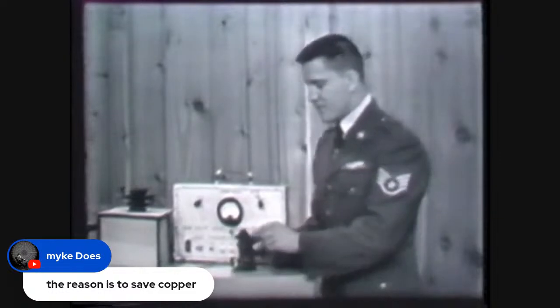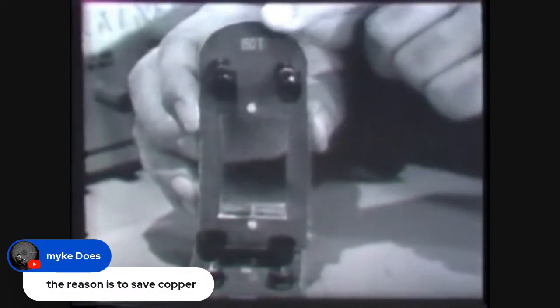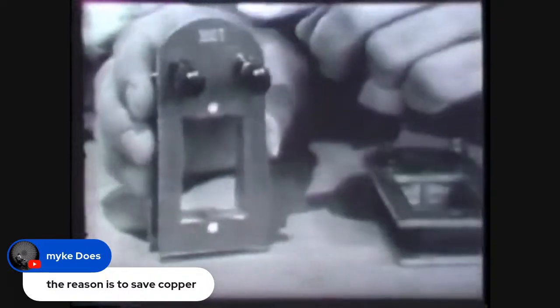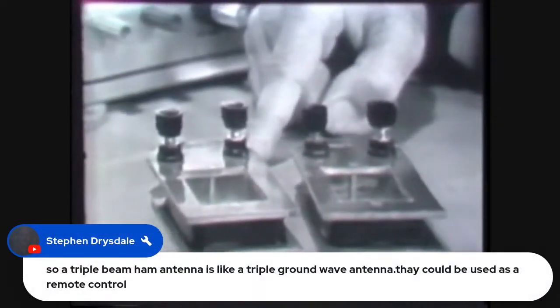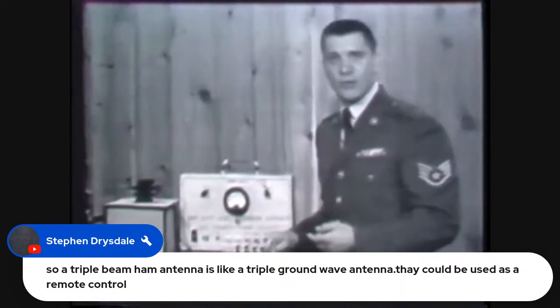One of these windings has 150 turns. Its normal resistance is 10 ohms. This winding has 300 turns. Its normal resistance is 20 ohms. The big difference in these two windings, however, is that one of them is shorted and one of them is open. So let's use our ohm meter and see if we can tell which is which.